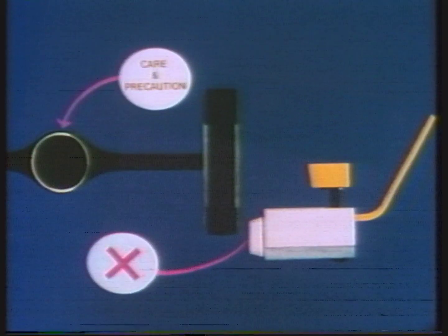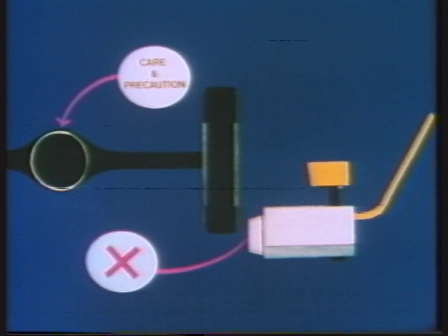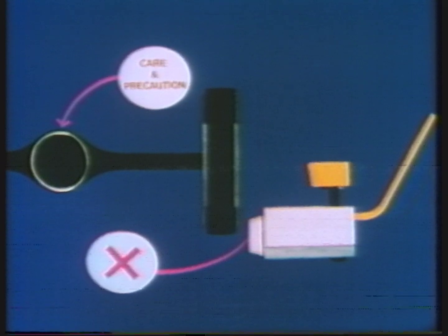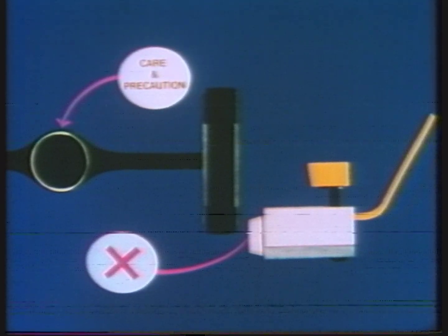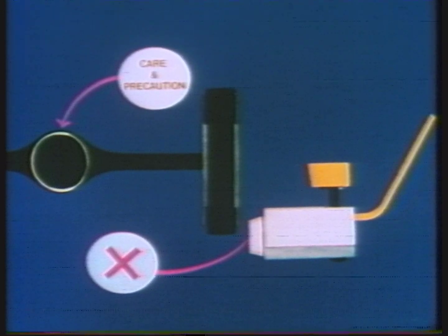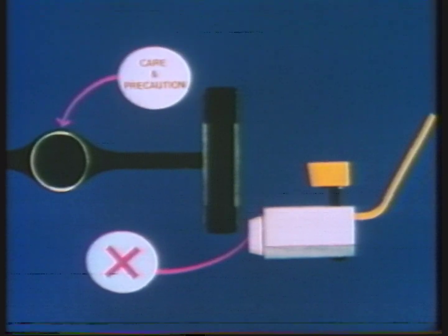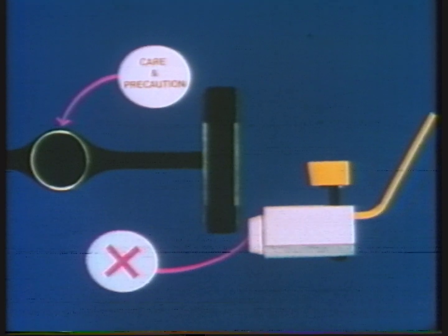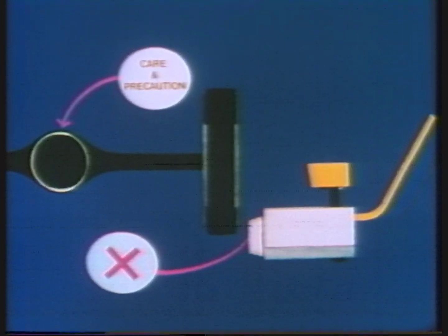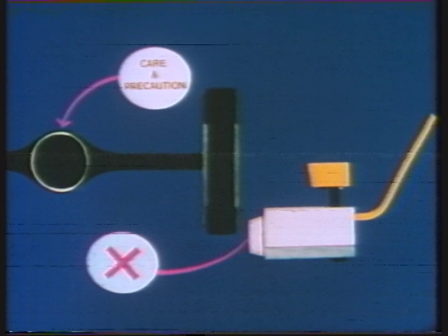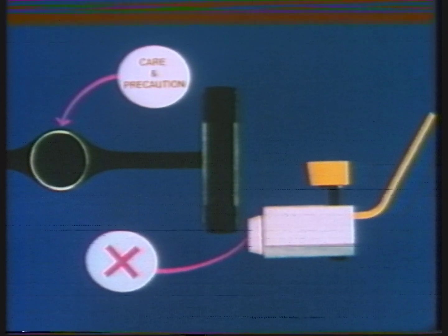Kinetic balancing of rear wheels is sometimes required, but the spinner must not be used to spin driving wheels. If balancing is to be done in situ, the engine must drive one wheel while the other is stationary. This means the differential gears are going to be driven in a manner for which they were not designed. Unless care and special precautions are taken, severe and expensive damage would be done to the customer's axle.